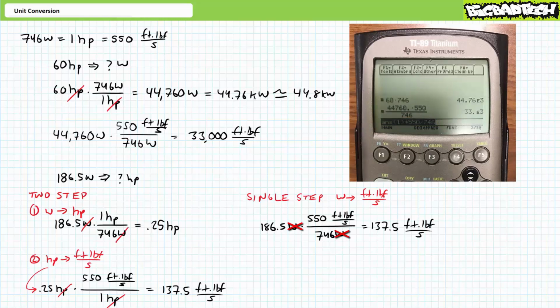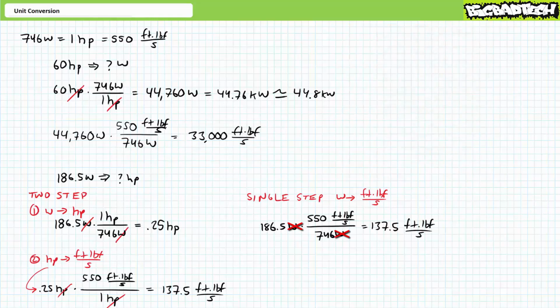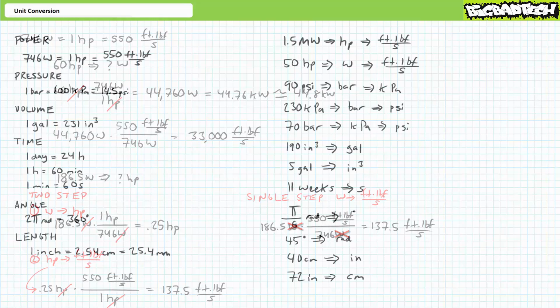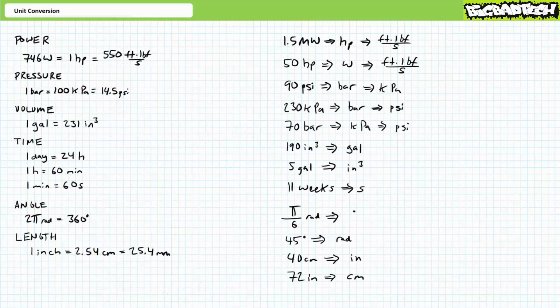If foot-pounds force per second employed engineering prefixes, you'd use a kilo prefix, but they don't, so we need to convert this back to the base unit. 33 E3 means 33 times 10 to the third, or 33 times 1,000, so our output expressed in the base units of foot-pounds force per second is regular old 33,000 foot-pounds force per second. Dig? I think the hardest thing for folks new to this game is determining which units use engineering prefixes and which ones don't. This will take some time and exposure. For now, don't worry about it because I'm going to tell you when it's appropriate to apply engineering prefixes and when it isn't. In that spirit, let's move on to some illustrated examples.